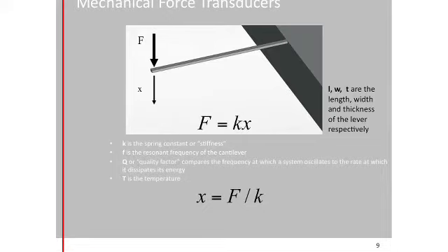Okay, so if you want to measure small forces, you might imagine that you need some cantilevers that have very, very small spring constants, very, very small k, such that even very small forces will create large measurable displacements. And that's basically the first naive thing you would think about. Let's just get a cantilever with the lowest possible k. Okay, and if you just run through very simple Euler-Bernoulli equations, and you find out how should I make my cantilever out of a given material in order to minimize k, you find that k goes with these geometric parameters. So the width, the thickness cubed over the length cubed.